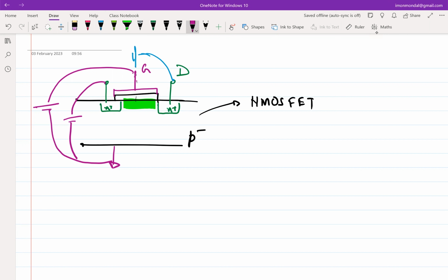But ultimately, when you are designing any circuit, there is only one reference node, and with respect to that reference node, you have to define the potentials of others, right? So if we simply say that I will make this a floating battery, then can you make a comment on what is the exact voltage at the source or the drain? I know the difference between the source and the drain is certain, whatever battery I have applied between it. But there is no way for me to ascertain whether the source is at a certain potential or the drain is at a certain potential.